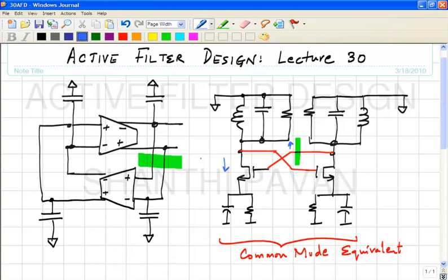let me call this capital GM of S times V, where capital GM happens to be, why do I say GM of S? Yeah, so we have to sit and figure out the transconductance of this composite block. All I'd like to say is that it is not the transconductance of the transistor. All right, and what would you expect the resistance to be? Would you think it would be high or low? We saw that it's a current source, so ideally it should be infinite. In practice, it will be a large number.